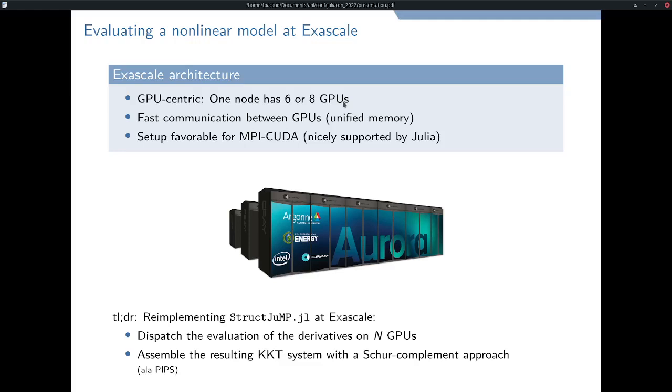So we will compute a number of batches, capital K for instance, or rather the computation of the K first power flow equations on one GPU, then the K plus 1 to 2K next power flow equations on another GPU, and so on. In that way, the evaluation of the model is fully parallel.